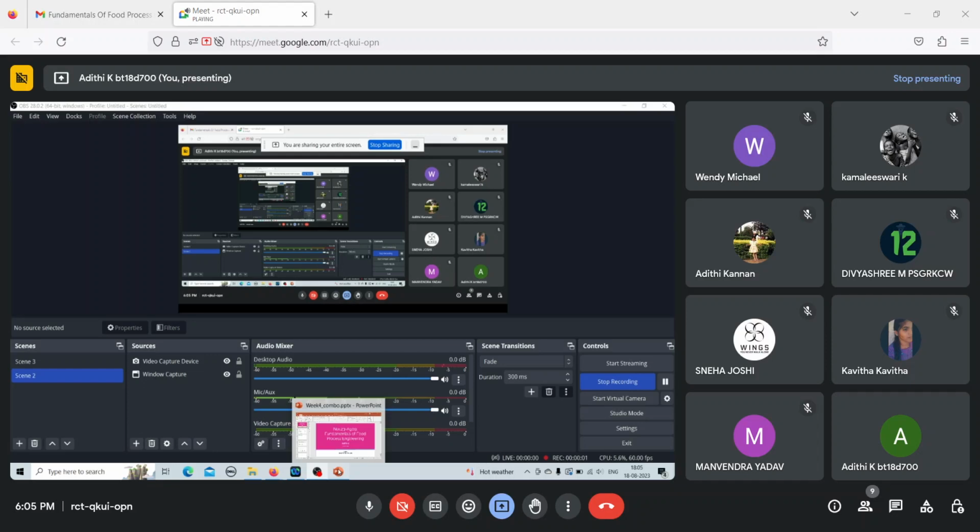Second thing, or more importantly, since they are not in contact, whatever steam you are sending in, you are taking it out. So steam is not included in the total mass balance equation. We include only the streams that correspond to your liquid food. So inlet is equal to outlet. That is what we have done here. Inlet, which is F, is equal to outlet, which is L plus V. This is your total mass balance equation.